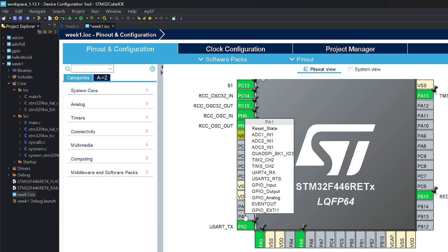As soon as it's ready to go and read the data, turn the other one on to the same input, then turn the other one on, and improve your sampling rate by using 3 different converters. We're not going to do any of that, but we're going to just look at one of them. But you could then say, I've got a potentiometer over here, I've got a thermistor over here, I've got something else over here, and use the 3 of them independently. Okay? And so we have all sorts of different ways.